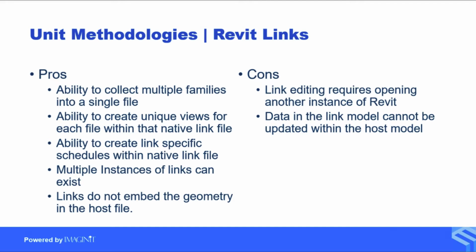We do have the ability to have multiple instances of links. So we can take that single link and copy it around 30 times in our project and only have 1 link to potentially update. Links do offer us the ability to keep our file sizes a little smaller, by not embedding the geometry in the host file. If our links get large, it could still offer some complexity, but it's going to help in the file size by having them linked.